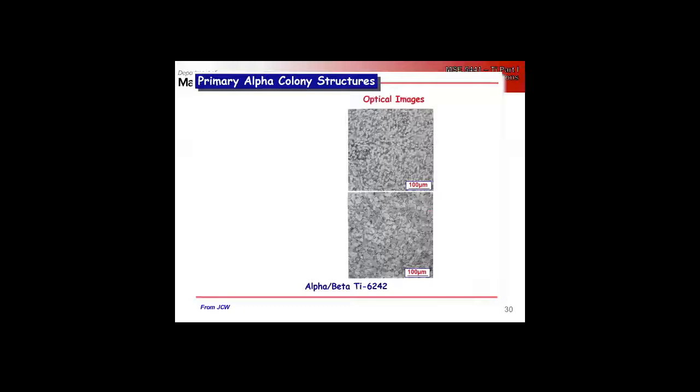And one of them will perform significantly better in dwell than the other. And the key thing is, can you tell any significant difference between these two from optical? I can't. You have a little bit of an over etch here compared to this one, but that's just metallography. That's just prep. That's nothing in the metal itself.